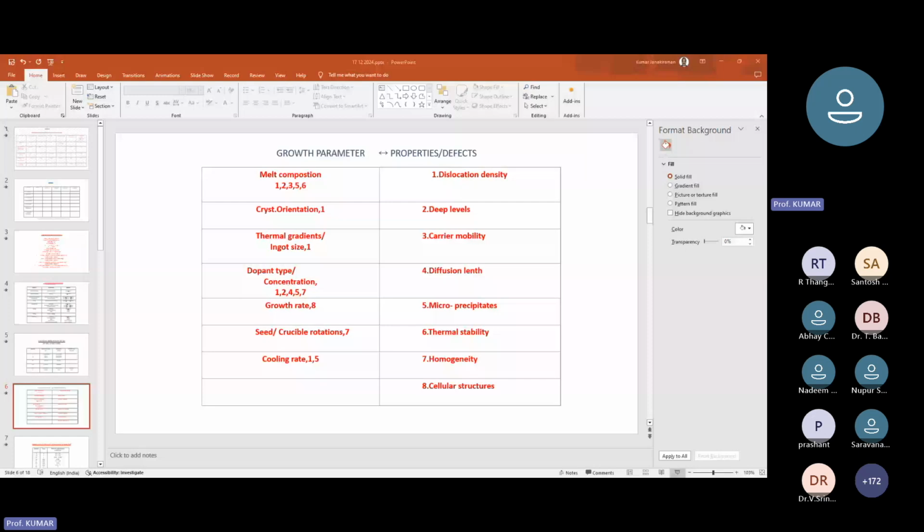One can use platinum wire, iridium wire, or alloys of these in order to produce good quality resistance heating. You can also use tungsten wire or tungsten sheet, which is what we are now using for growing alumina crystals. We can use induction heating, as I said, and we can use various other types of heating also. One of the important things is that for most of these heating elements, we need a good container, whereas for arc image heating, we don't need a container, which is done, for example, for materials like zirconium oxide or magnesium oxide.